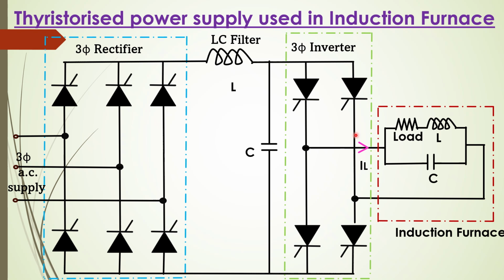performance of the induction furnace, or nothing but to maintain the temperature constant in this furnace. So this is obtained by these voltage and current levels, automatically controlled through the thyristorized bridges employed here, and the induction coil in series with the resistor maintains the current constant. So this is the purpose. And also the capacitor in parallel, as I mentioned before, is used to improve the power factor. So the main feature of this power supply is that the inverter circuit does not have any commutating circuit.